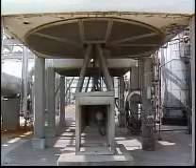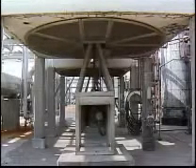To increase the amount of heat transferred to the air, the fans in the cooler can be started. This increases the airflow through the cooler, which increases the amount of heat that is transferred by convection to the surrounding air. As an operator, you may be required to operate many types of heat exchangers.